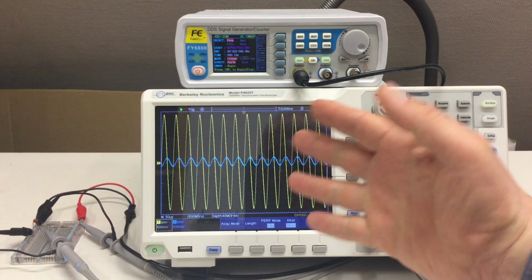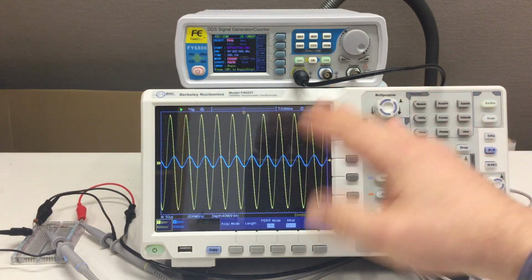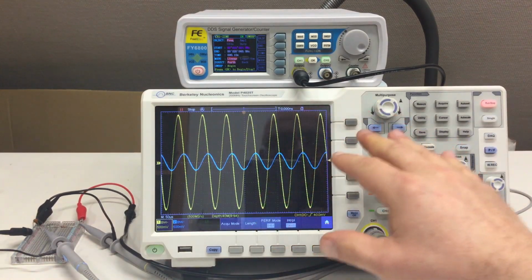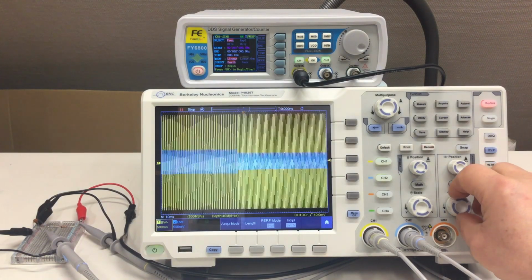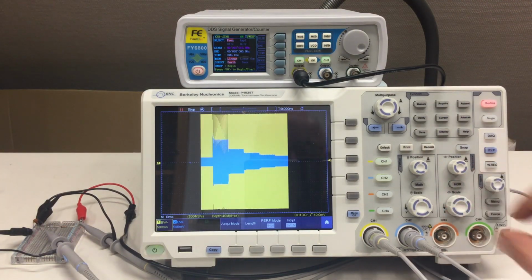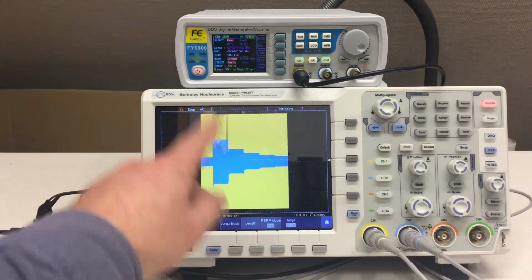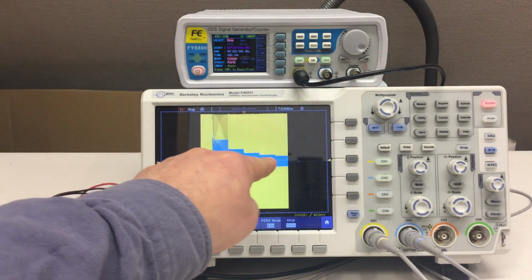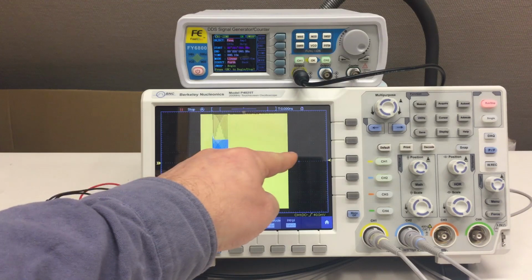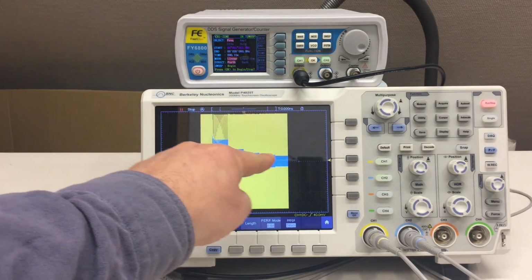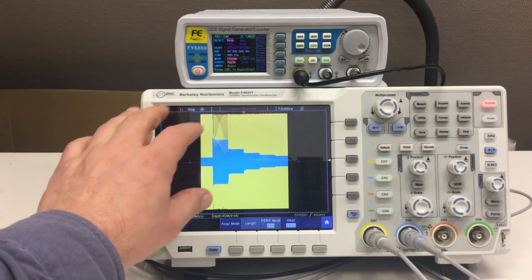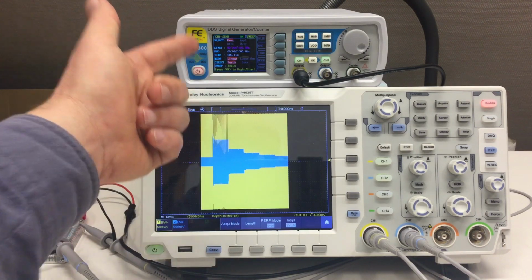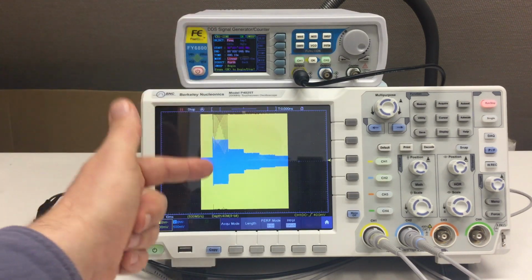And on the oscilloscope, you see some funny things are going on, of course. But if I press stop, and my sample length is 40 megasamples, and I squish the time scale together, we get, this thing is not working perfectly, but we get, at least in the amplitude, and that's what we will aim for in this video, the frequency response curve. Obviously, it's far from perfect. The reason being, that thing is not really synced to this thing here.